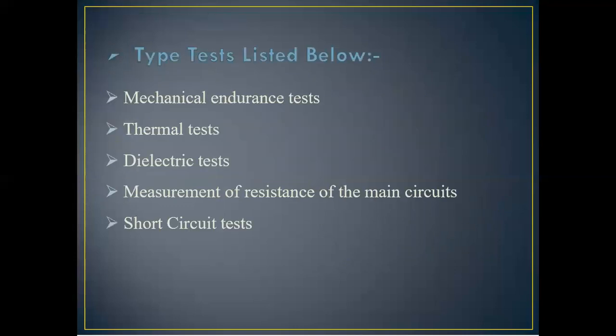Then type tests are listed below. First one is mechanical endurance test. Second one is a thermal test. Third one is a dielectric test. Fourth one is a measurement of resistance of the main circuit. And fifth one is a short circuit test.